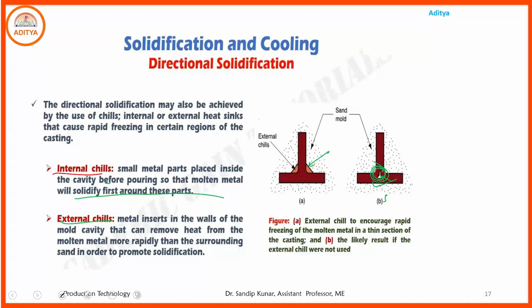In that case, more heat will be extracted from that particular surface, the place of the external chills, in that area. Chills are used for directional solidification, as they remove more heat from that particular surface.